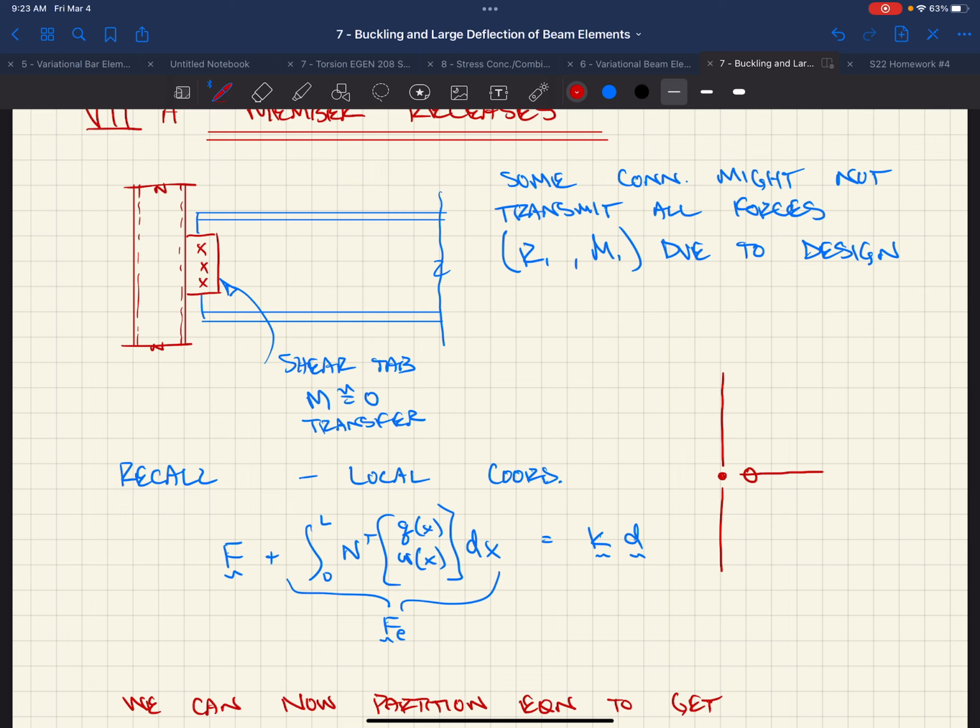Is you'd go back through, take all of the readings in VA, and then you go through the table in the steel manual, right? And make sure that there weren't any connections that exceeded that demand in the table values, right? It doesn't happen very often. You have to have certain circumstances for that to happen. Usually you have way more capacity. So even if you got to ultimate loads, you're going to be far below the actual capacity of the connection. And so the chances of it even yielding at that point is probably pretty slim.